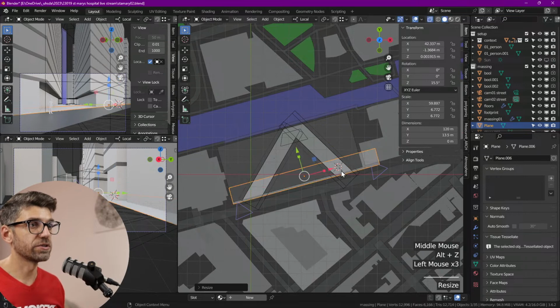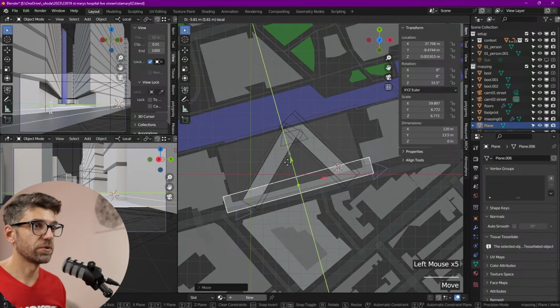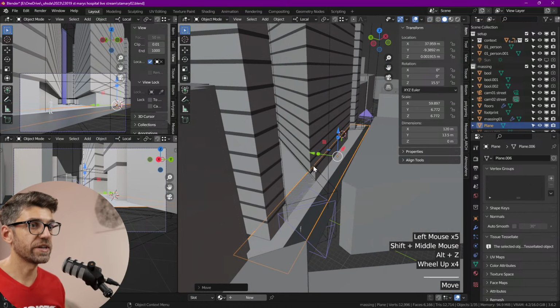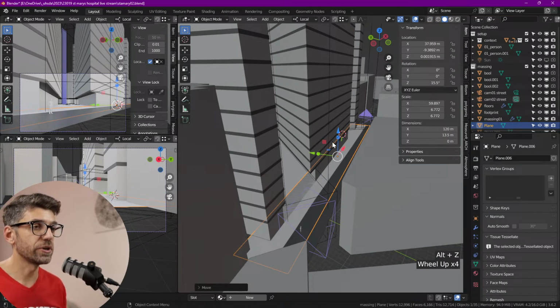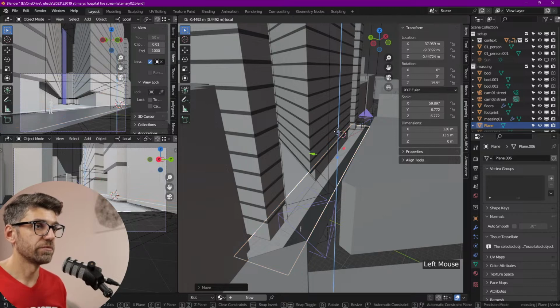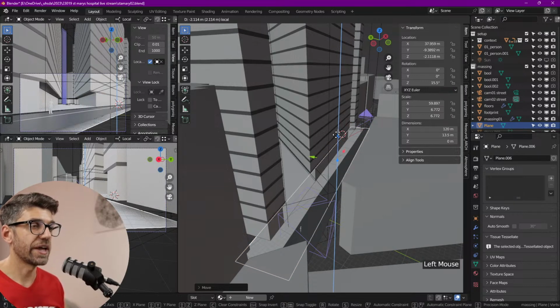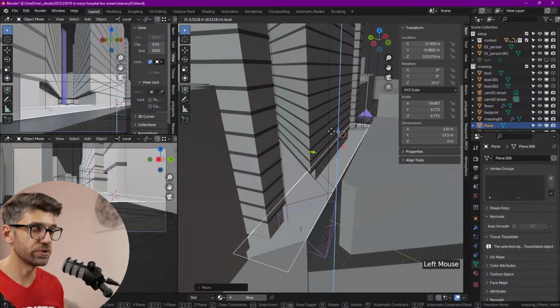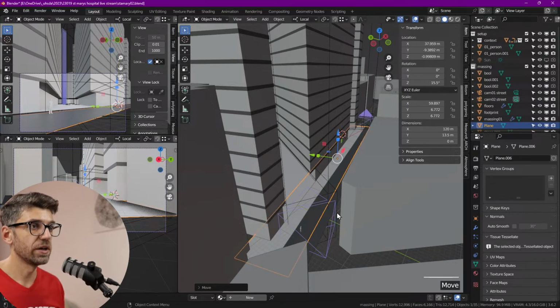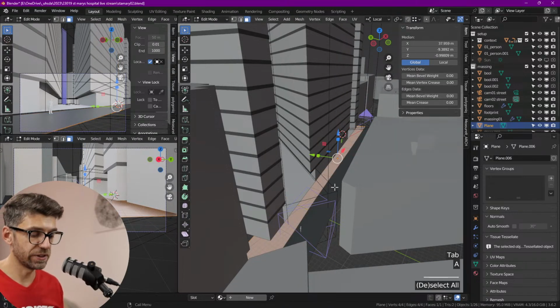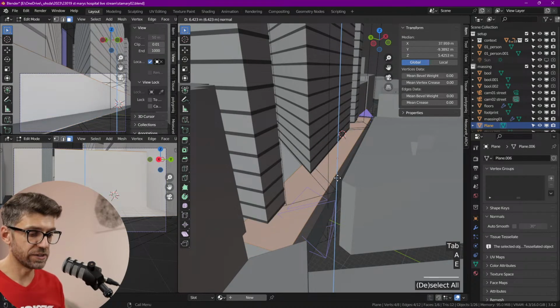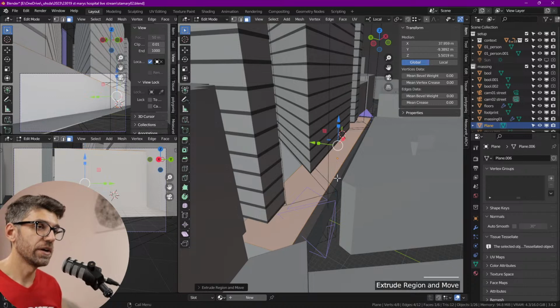So that grows a little bit more. So something to around this size. Doesn't need to be exact. In fact, it's better to go a little bit below so the booleans work a little bit better. Sometimes there's issues if we have an edge that's exactly intersecting at the same position. So I'm just going to go -1. Go into edit mode, select everything, E to extrude, and let's type in 6.5 because we went down 1 and now we want to go back